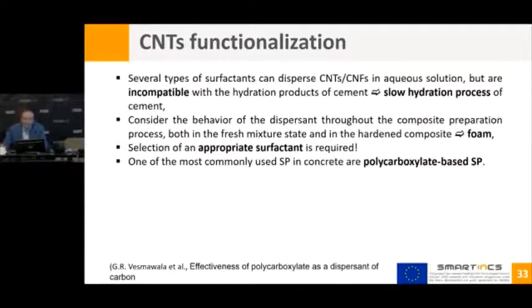Of course, you have to take care when using this kind of surfactant of the possible interaction with the hydration products of cement, because some of these products are very efficient. You have to take into consideration that once you have correctly dispersed the carbon nanotubes into water, if you work with cement, your work is not finished, because then you have to take this solution and add cement.